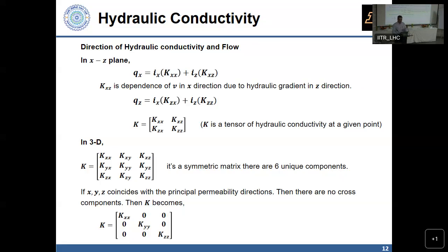So this transmissivity encompasses all the heterogeneity or stratification that you have in the z direction. Again, it will be a tensor, but the same rules will apply. Even for the 2D field, it's a matter of whether it's aligned along the principal directions or not. If Txy and Tyx can be ignored or compensated for, then you'll have two principal directions, Txx and Tyy, or two parameters to worry about.